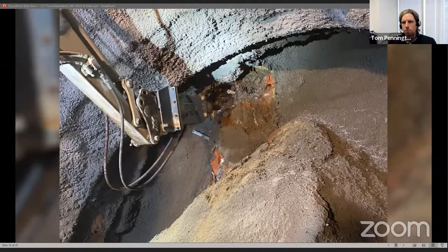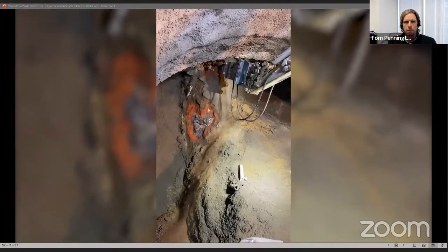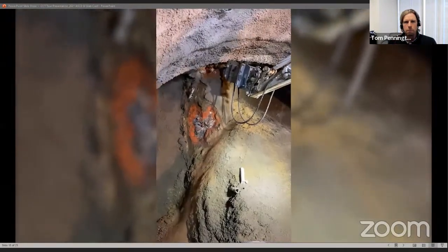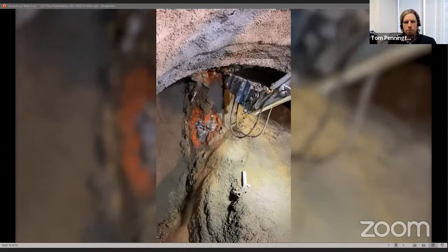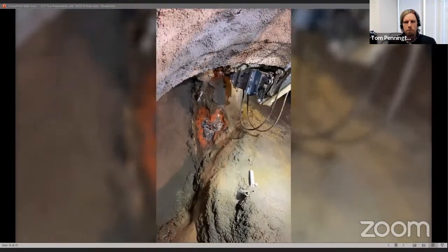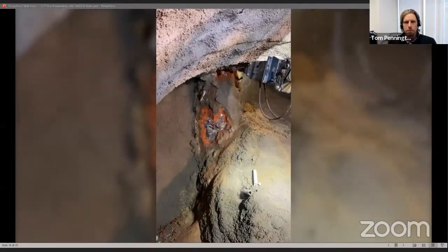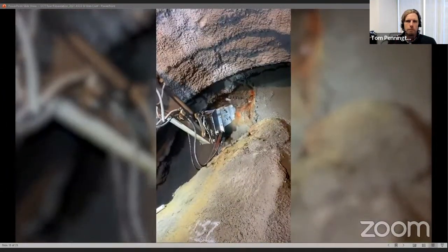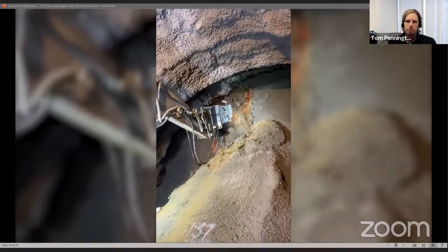The second challenge presented itself just beyond the tunnel breakout from the shaft. While drilling the canopy pipe array, 2 pipes encountered brick. The canopy pipes were eventually drilled through the brick, and tunnel excavation resumed while soil samples were analyzed for contaminants.